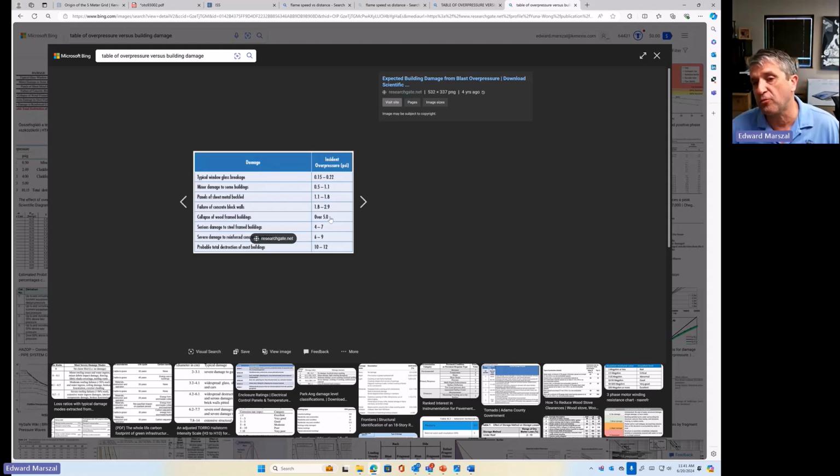So how big of a pool are you going to get? Then we will run a vaporization model to figure out what vaporization rate we're going to get off that pool, and a dispersion model to figure out how big the gas cloud would be, and use scenario coverage to lay out our gas detectors based on that dispersion modeling. So that's the high end of what I would recommend.